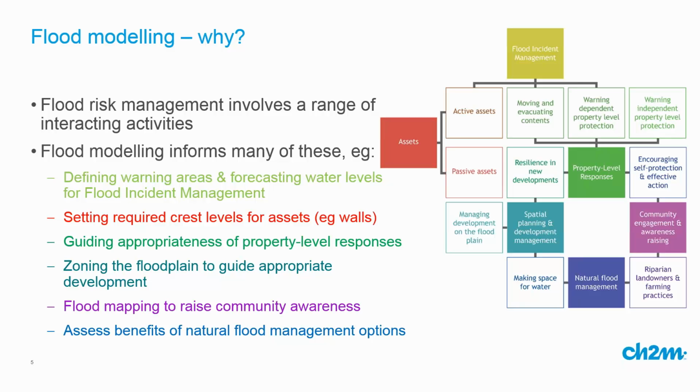So if we now think about those 6 items and think about how flood modelling is involved in those, starting with the flood incident management. Flood modelling is used to define flood warning areas, the areas where flood warnings are going to be issued, and it has got a really strong use there in terms of forecasting water levels at points from which a flood warning can then be issued to that flood warning area.